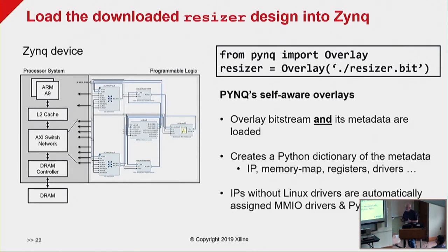And we do further tricks to enhance the user experience. So for example, we bring down not just the bitstream, we package that, but we package the metadata. Now that can be the Tcl file or the HWH file, or there's now an XCLBIN file, there's another format coming. And from that we can extract the metadata of the design. And again, I think Jay said this morning about how metadata can be very valuable and how you can enhance the user experience with metadata.